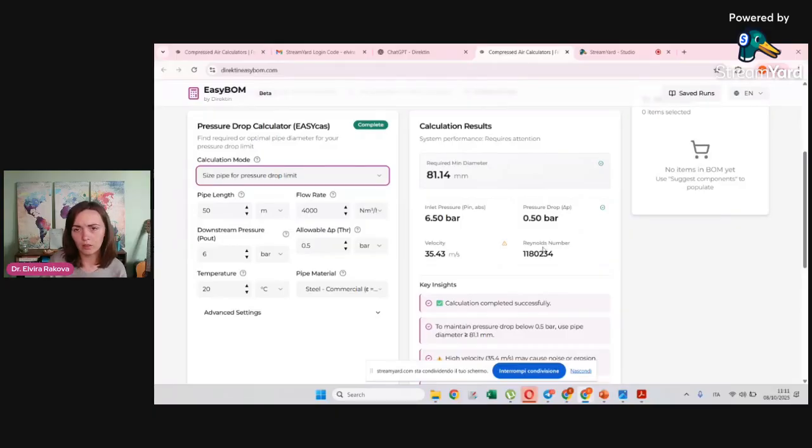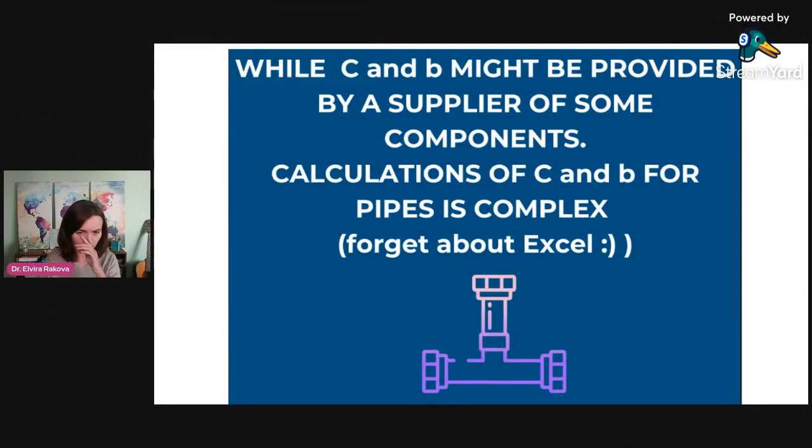But what we also had the conversation about, and what is extremely important, is that on the stage there were some discussions, some comments about what if the pipe is undersized. Okay, it's all clear, the pressure drop is too high, so everyone knows that it has to be replaced, and this is a restrictive component. Meaning that the sonic conductance is not good enough for this application, for this mass flow rate. What if we now think the pipe is too big?